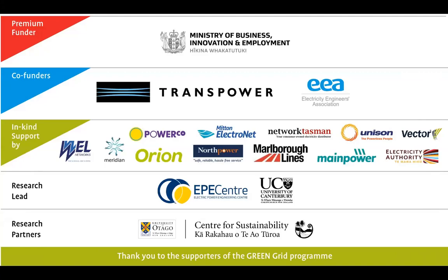We got a question from Kate here, which says, do you have any information on daytime charging as more businesses provide charging on site for employees? Yeah, that's something I definitely have considered, but haven't really put into action yet. As I said, I do a simultaneous model of the EV batteries alongside the load flow simulation. It's quite a simple simulation of the EV batteries. They have a state of charge when they depart in the morning. I then pick a distance travelled, a round trip distance to their work and back, and then I calculate the state of charge on arrival.